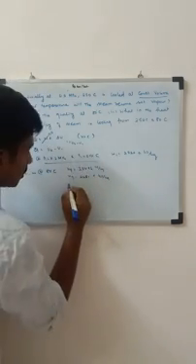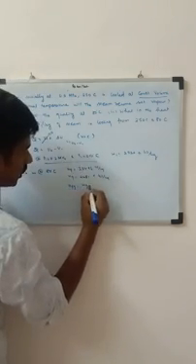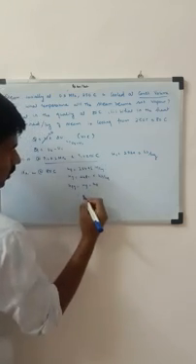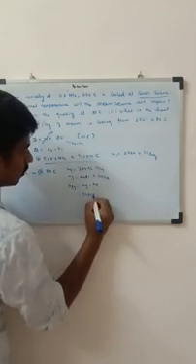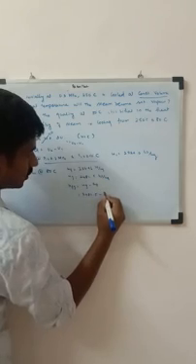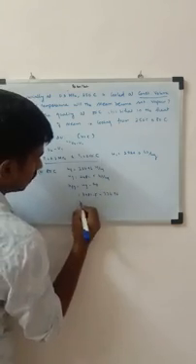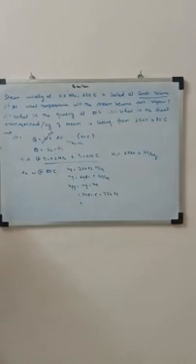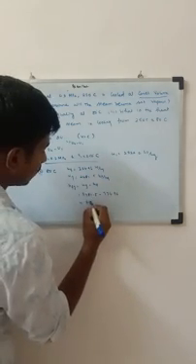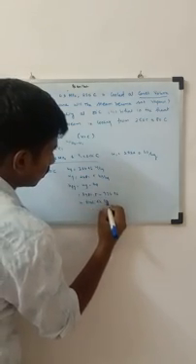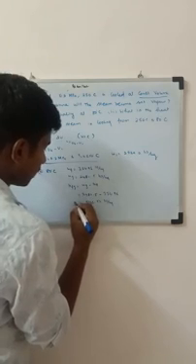And we know that UFG is equal to UG minus UF. Therefore I subtract this from this. So 2481.5 minus 334.96. The value that I get is UFG is equal to 2146.54 kilojoules per kg.